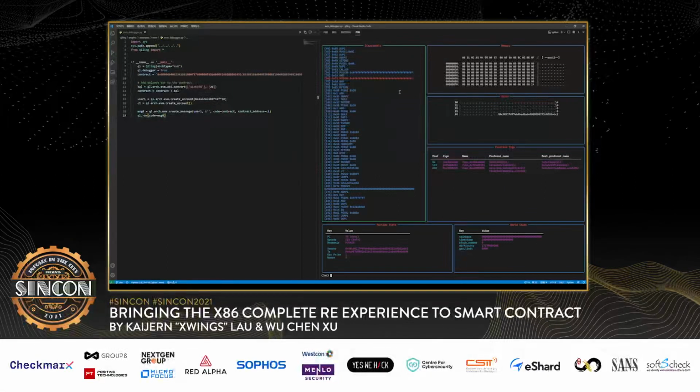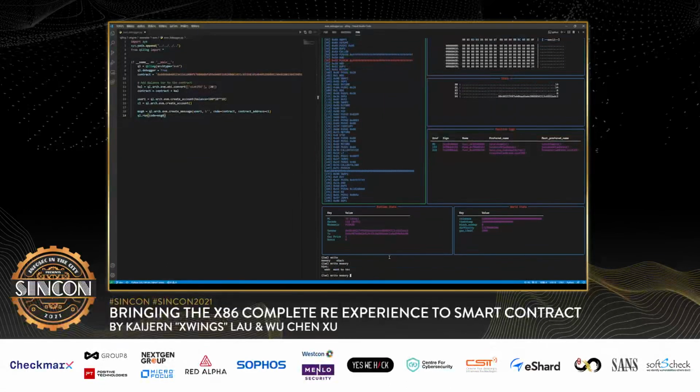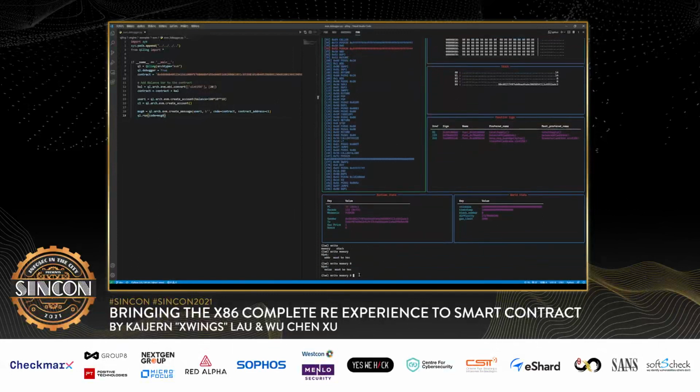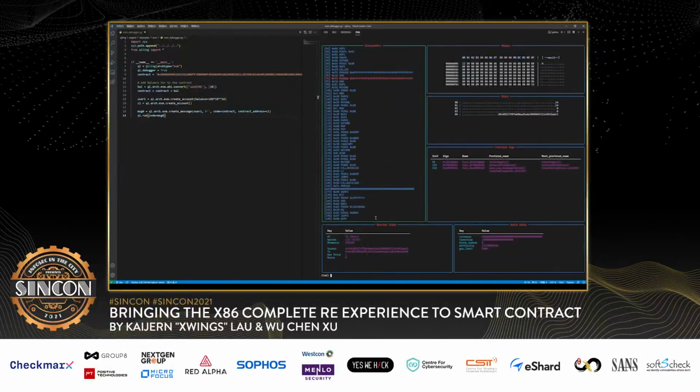We also support writing memory and stack. Just use the write command. For example, we can try to write memory. To write memory, we need 2 parameters: one is the address and the other is the values. Here we write 1, 2, 3, 4 to address 0, and now you can see we wrote it successfully.